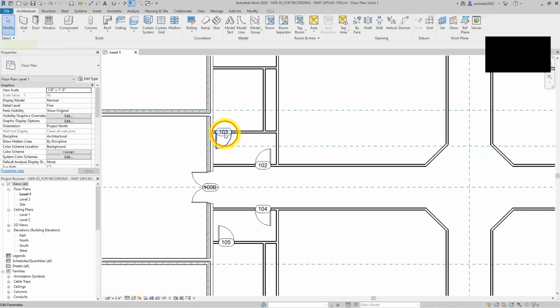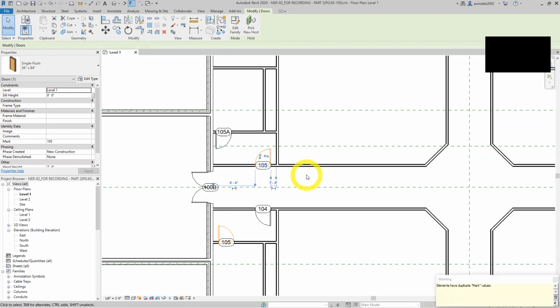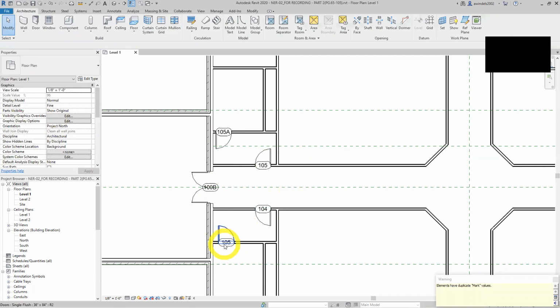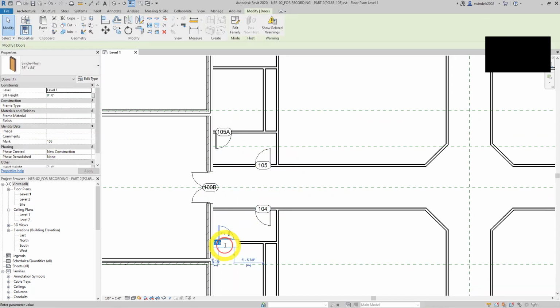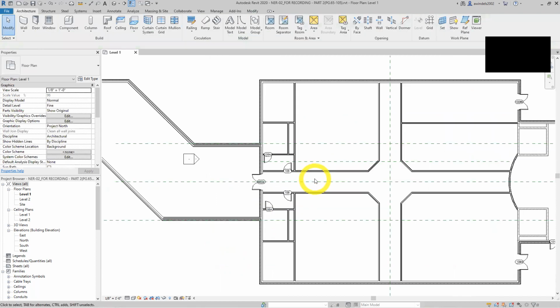And in the book, they had you go in the tags. A lot of blue stuff is editable in general in Revit. Grayed out is not, oftentimes. So I have a 105 already. Yeah, down here. So let's go in reverse order, because it will do redundancies, but it'll warn you with some of this stuff with schedules, which is helpful. Helps defeat human error. We're going to go to place openings in our wall.